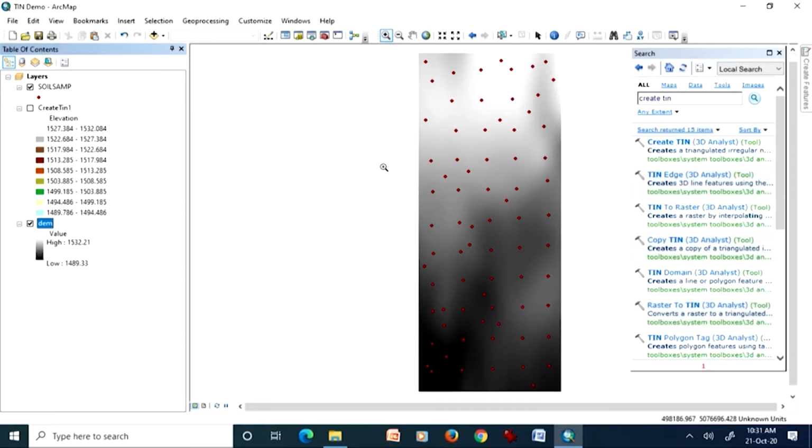I mean here is whether you want to stay within your data file or input data extent, or you want some extrapolation also. So, I could have generated the same points with a DEM covering a large area, but then that means I have created an extrapolated surface, not an interpolated surface. But if I am keeping my digital elevation model within my extent, then it is really under control, and not much extrapolation has been done here.